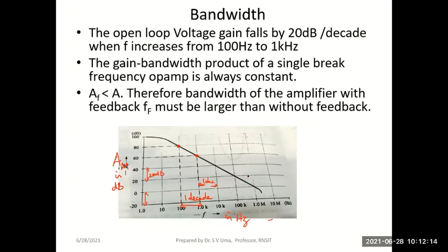The op-amp, ideal or practical op-amp, has a frequency response which looks like this. And you can easily see that though we say op-amp should give us high gain, it gives us very high gain only at some low frequency range. So it gives you a gain of 100 decibels only from 0 to 10 hertz, as you can see. After that, it's again falling constantly. So actually nobody uses any amplifiers within 10 hertz range. Yes or no?